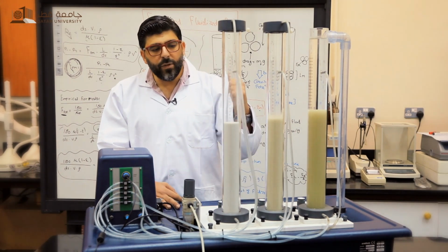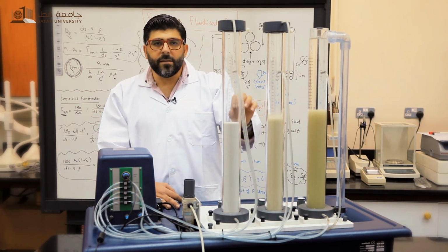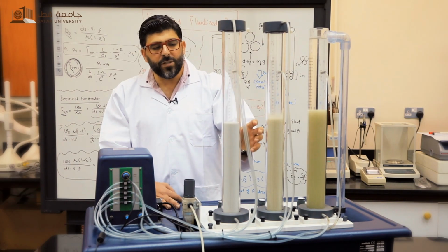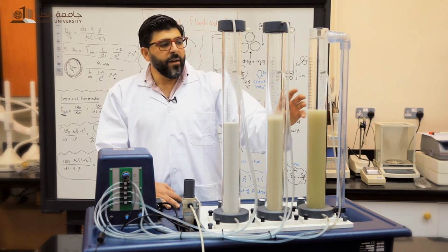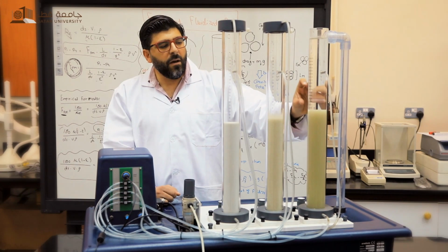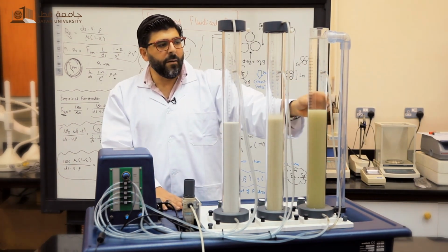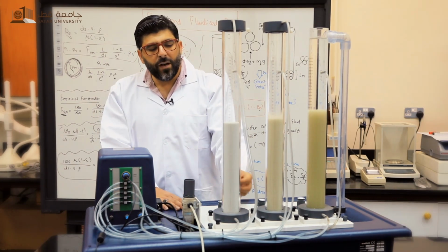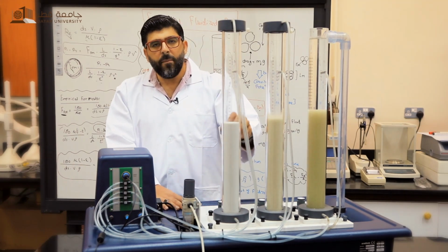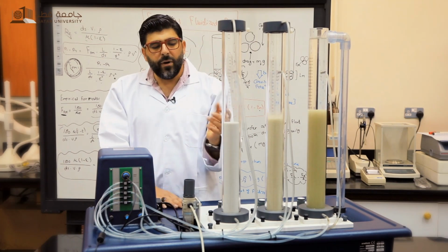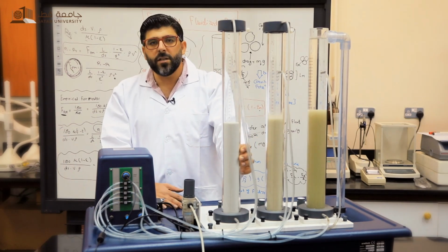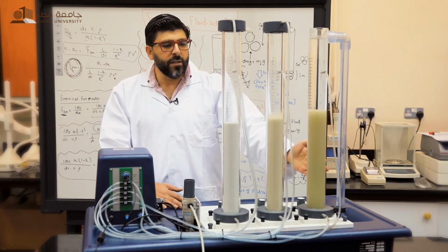Now, as we said before, when air is the main fluid of the fixed and fluidized bed, the fluidizing process is bubbling. Here the fluidization is particulate, because it's like the particles are swimming in the fluid. Here it is bubbling because the gas tries to escape from the bed itself. When the gas comes from down to up, it drags the particles up until it escapes, so they come down again. So here the fluidization is bubbling, and here the fluidization is particulate.